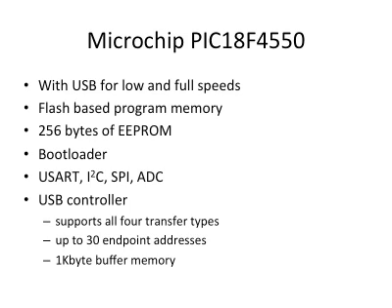And in that mode, new application firmware can be uploaded to the chip through the RS-232 interface, and the bootloader will write the new code. We're talking about application code to a specific section inside the microcontroller. So inside the microcontroller, you essentially have 2 segments of code: the bootloader itself and an application code.